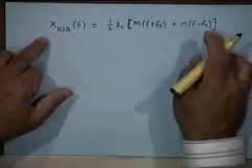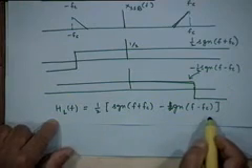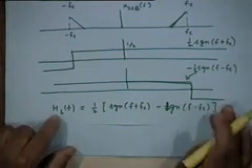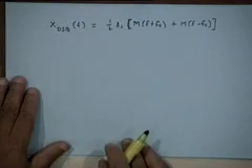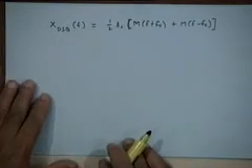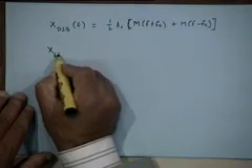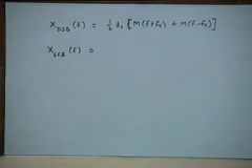You are multiplying this spectrum with this transfer function to produce your SSB output. Agreed? If I multiply this transfer function with the DSB-SC spectrum, which is this, I will get my SSB spectrum. So therefore, my expression for the SSB spectrum in the frequency domain can now be written in a closed form.